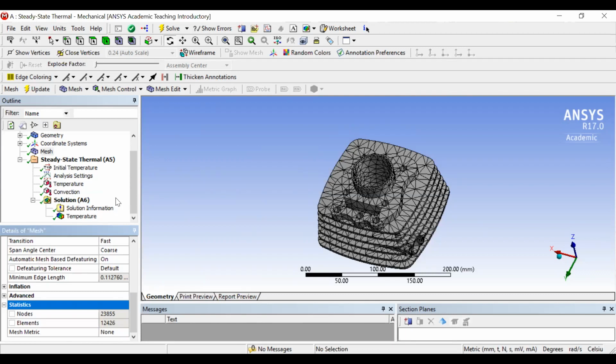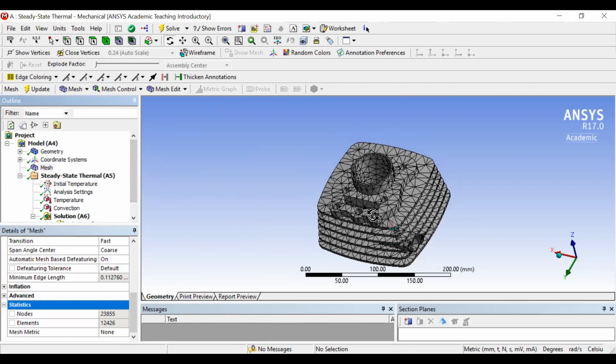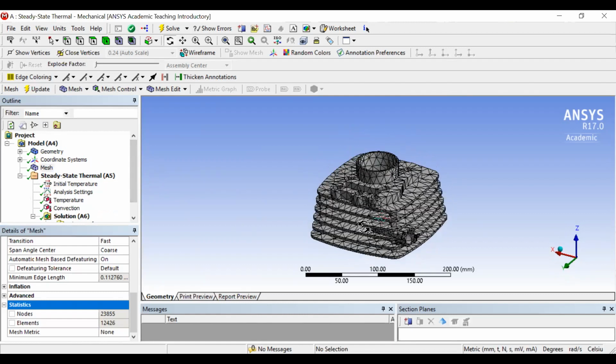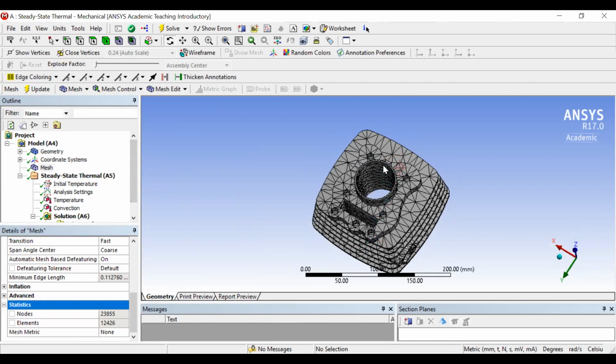But again, if you are interested in giving a better mesh, you can use all the nodes which I've shared for meshing. You can try to refine the area of interest. Go there, refine the mesh down there, give some face meshing. That's the other option we have.